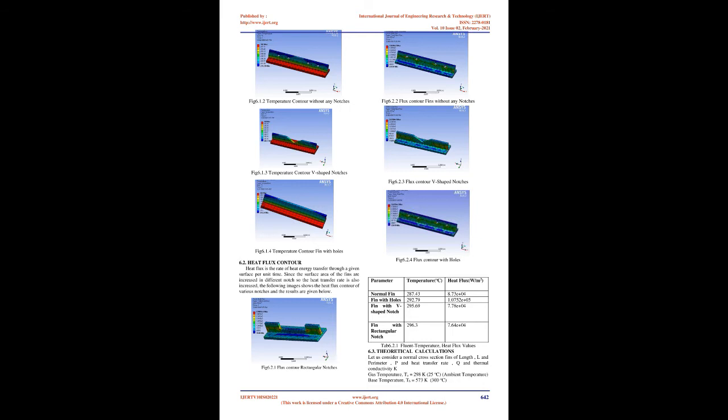CFD analysis and mesh generation. Computational fluid dynamics, CFD, is the science of determining numerical solutions of the governing equations for fluid flow through space or time to obtain a numerical description of the complete flow field of interest. The equations can represent steady or unsteady, compressible or incompressible, and inviscid or viscous flows, including non-ideal and reacting fluid behavior. The particular form chosen depends on the intended application. The state of the art is characterized by the complexity of the geometry, the flow physics, and the computing time